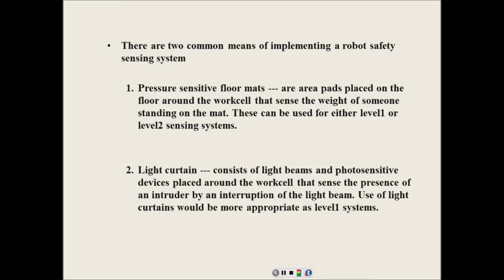Light curtains, these are very, very popular. A light curtain is nothing but a lot of infrared lights. You can't see them if you look at them because they're infrared. And then it shoots beams across, and we have a bunch of photo detectors over on the other side. And it forms a curtain.